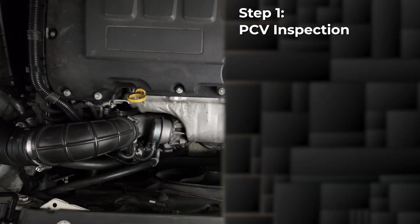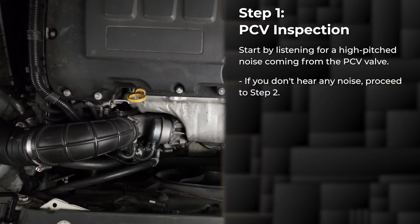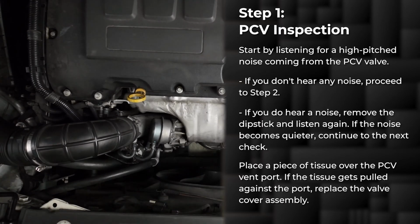Step 1. PCV inspection. Start by listening for a high-pitched noise coming from the PCV valve. If you don't hear any noise, proceed to step 2. If you do hear a noise, remove the dipstick and listen again. If the noise becomes quieter, continue to the next check. Place a piece of tissue over the PCV vent port. If the tissue gets pulled against the port, replace the valve cover assembly.